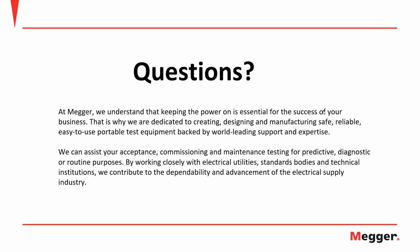The answer to this is no. A sealed transformer does not need to be vented before you take the sample. In fact, you want to avoid venting a sealed transformer because you don't want to expose the conditions inside the tank to atmosphere, and that's to avoid pulling in moisture and other contaminants. So no, you don't need to vent the transformer before you take the sample.